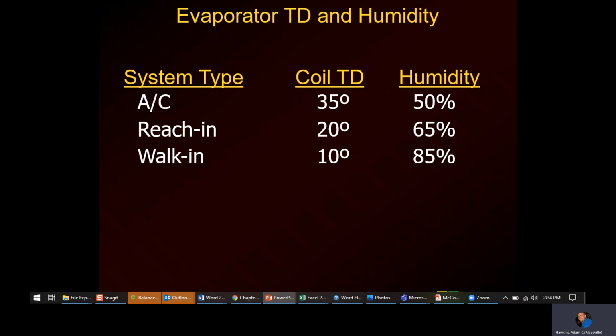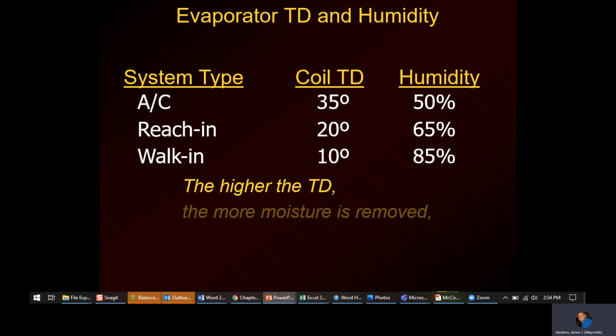So if you can dry that room out a little bit, it'll actually help evaporate the moisture from your skin, kind of like a fan blowing across you. Even though the fan is just blowing the temperature of the air in the room, it creates this evaporative cooling effect. So you want that humidity to be right. If you're running anything over 55%, 60%, you're getting in danger of creating mold and not healthy air.